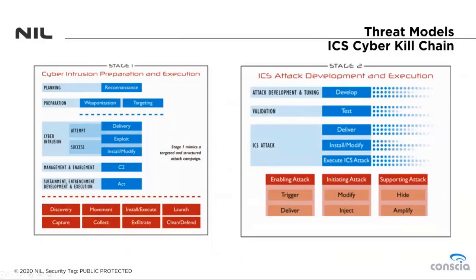One which is quite popular is the cyber kill chain. Maybe you heard of the cyber kill chain, but here in ICS, we have, of course, an ICS cyber kill chain. The difference is that we have 2 stages in the ICS version. To summarize, the first stage is about getting in and preparing the attack. The second one is executing the attack. The ICS cyber kill chain can help us when we're trying to define at which stage attackers are and what will be the next move.